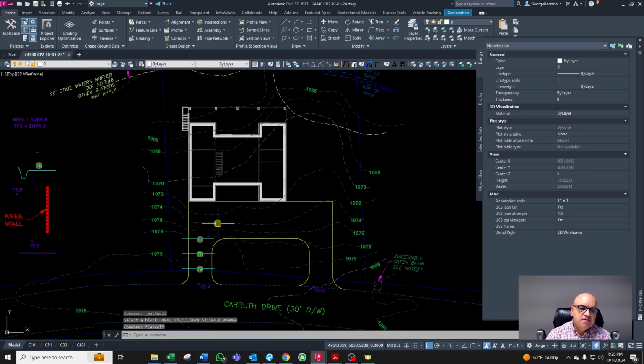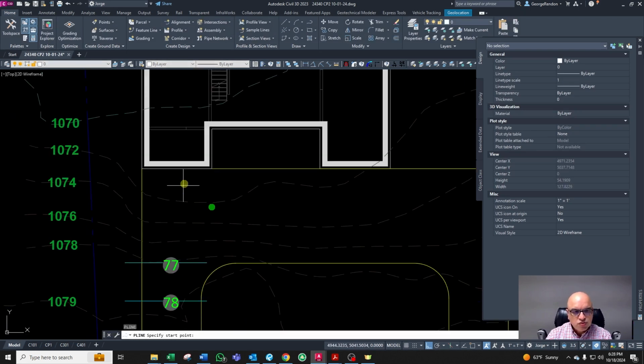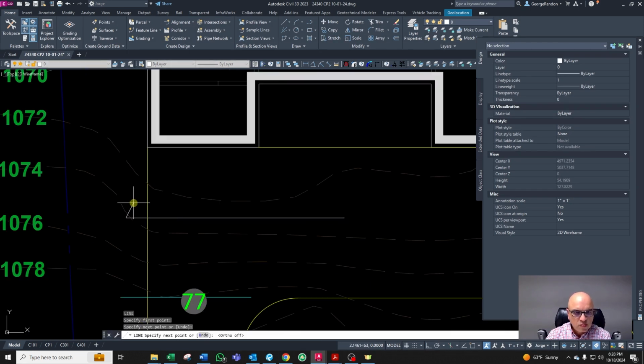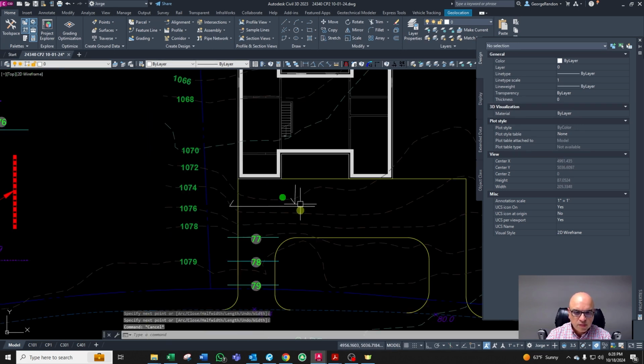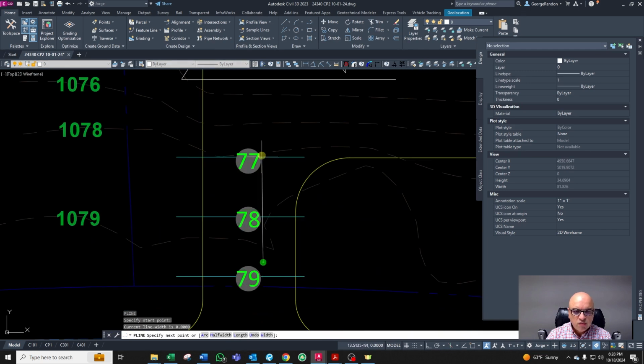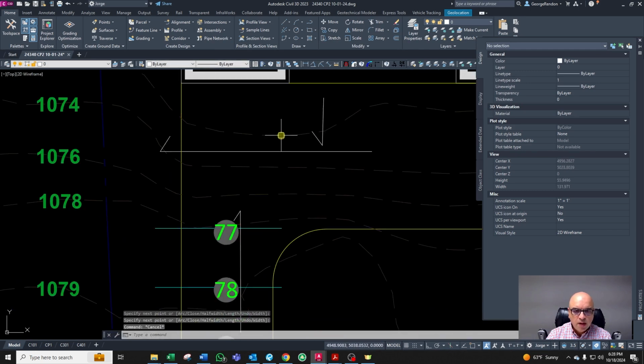Now what happens is this. The house needs to drain. We're gonna create like a swale right here. So the house will drain to that swale, and then the driveway would drain to that swale, and then this water would go in that direction.